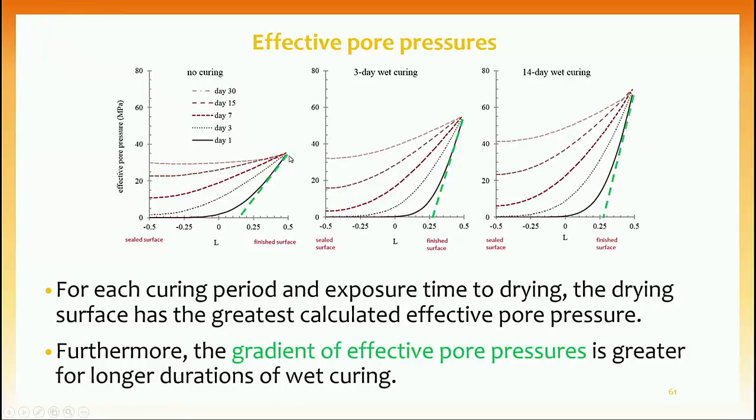And this green dashed line shows the rate of effective pore pressure, which I talked about in the strain equation, and it shows that the rate or the gradient is also increasing as you increase the duration of wet curing.